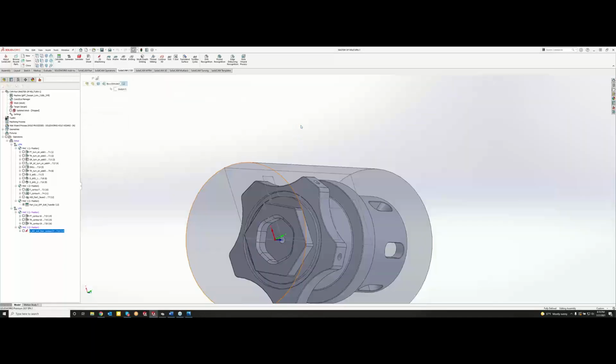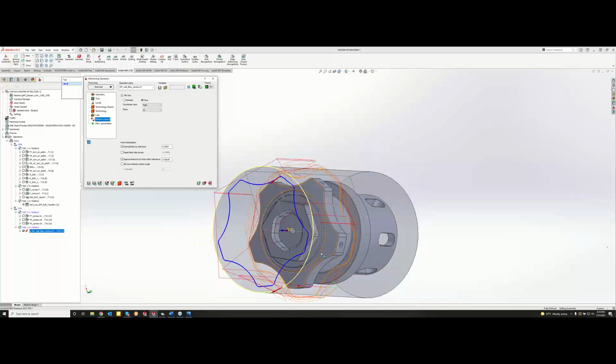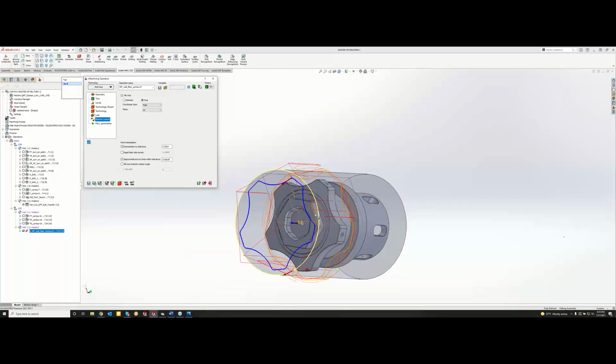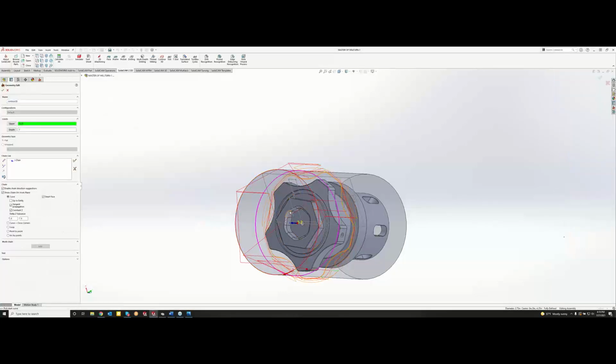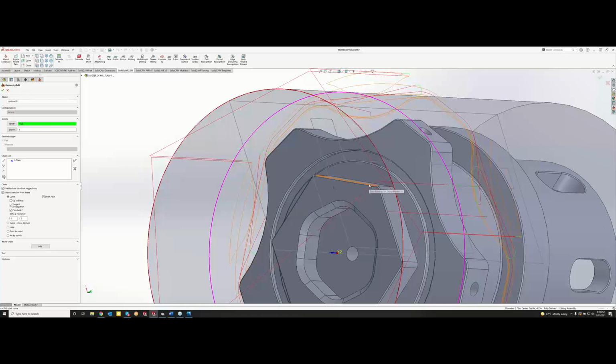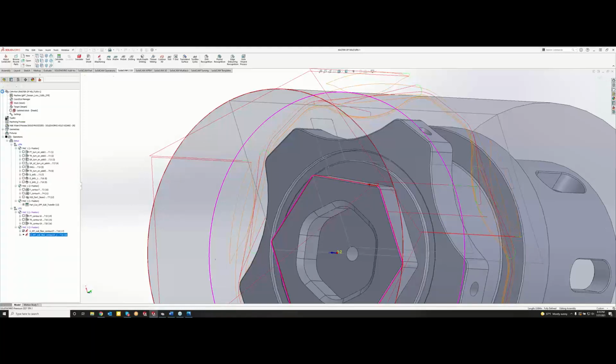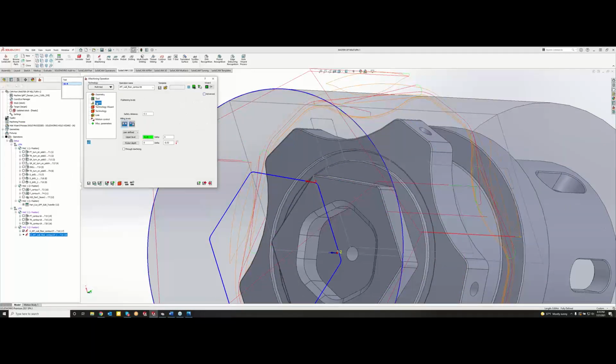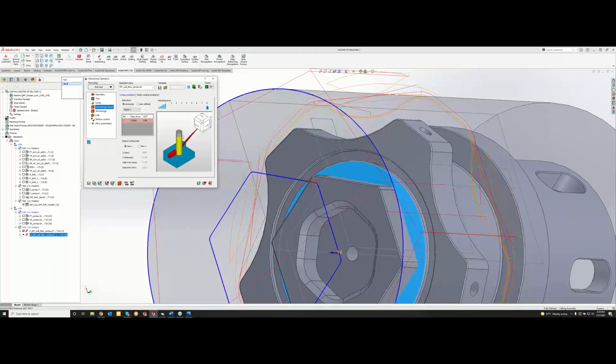Okay. So now I'm going to use that exact same tool path and everything to do my hex right here. So what I can do is just do save and copy. And then my geometry, I'll grab my stock again, as well as our smaller hex here, going around. And our tool is already set, so we're good there. And we're going to start at 0 and machine down to this face. Technology, we look good. We're running level 8. Go ahead and save and calculate here.